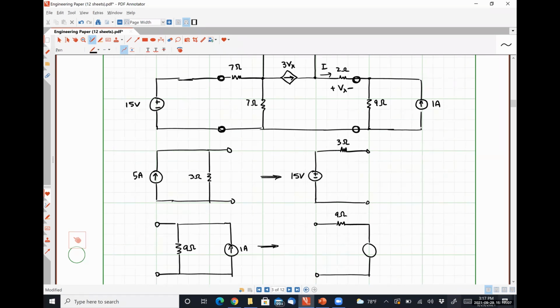If this were back at 4, I could have put the 3 ohm resistor down here. That doesn't make the 3 ohm resistor and the 4 ohm resistor any less in series, because all 3 of those elements are in series. So I could still combine 3 ohms in series with 4 ohms, which looks like 7 ohms.